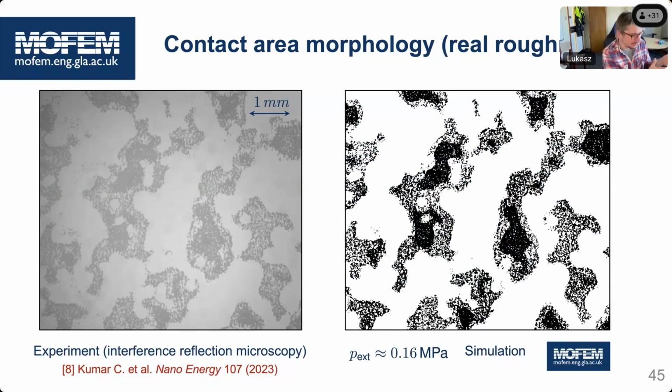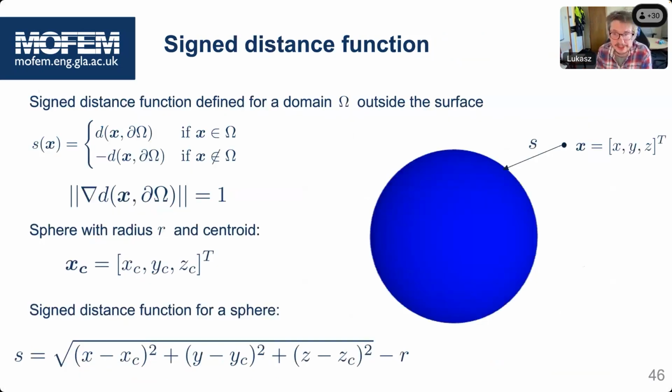We can add this L2 space, hybridize the L2 space on the skeleton, on the faces where we expect to have a contact, and then we can use that hybridized displacement on the boundary to enforce the contact boundary conditions. Very quickly, I will show you an example with a rigid body. We model the rigid body by an SDF, and we have a Python function where you can put an arbitrary SDF and have a contact with that.